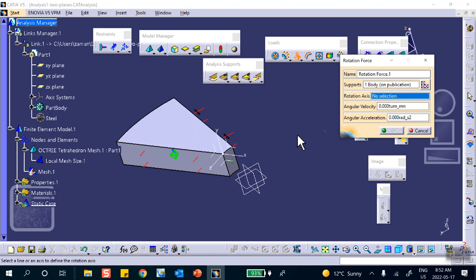Good. Unfortunately, it won't let you take the z-axis. You see that? Usually when you right-click, you're absolutely right, z-axis. But remember, the z-axis of the global system, not that guy. The global system axis, coordinate system was over here at the global origin. But unfortunately, you don't have access to it. Okay? So you're missing a line there. You can create a line if you want, or you can create the global coordinate system there. It's already there. It's just that I have to have access to it. So this is why we can't go any further with this.